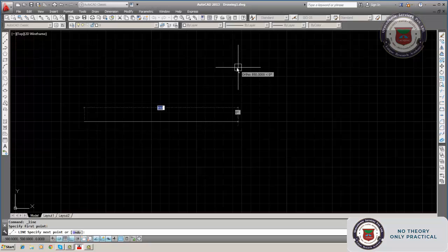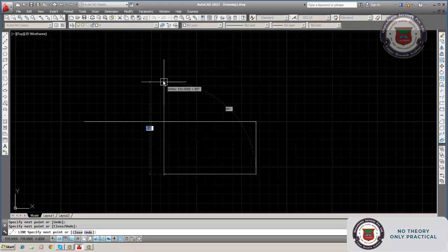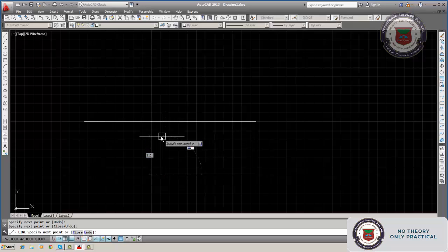It never moves in the angle. It always moves either horizontal or vertical. See, non-vertical, non-vertical. But you can draw a line in any angle direction by inserting the values here. For example, say I want to draw a 32-degree line. You can draw it, but if you insert the value manually, then you cannot click it. See here.